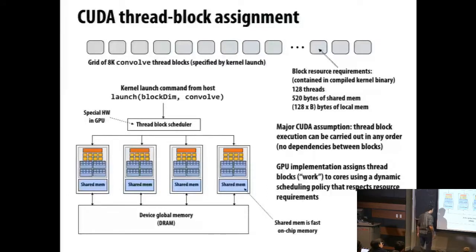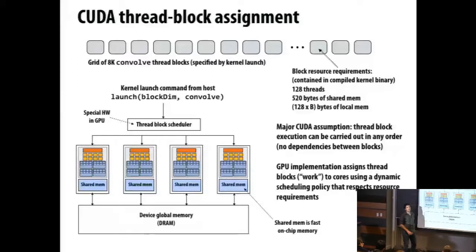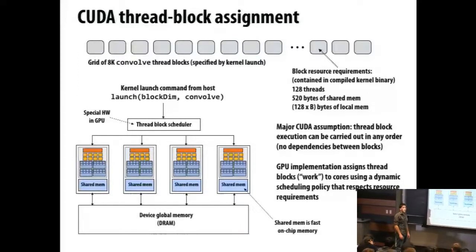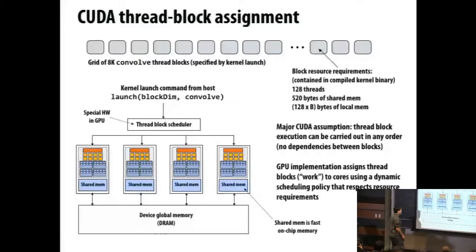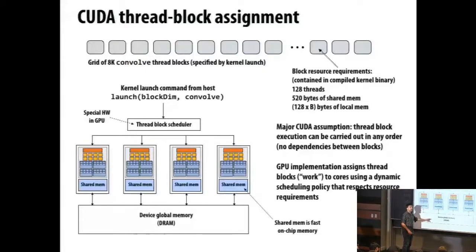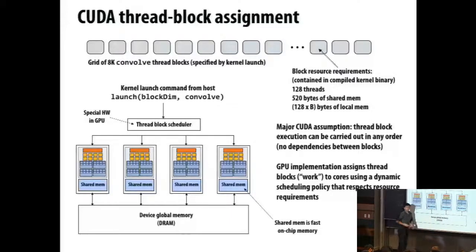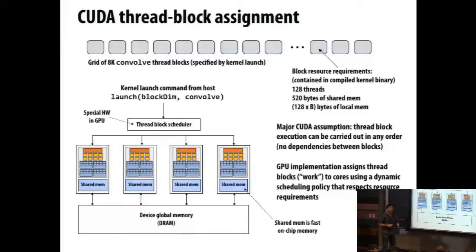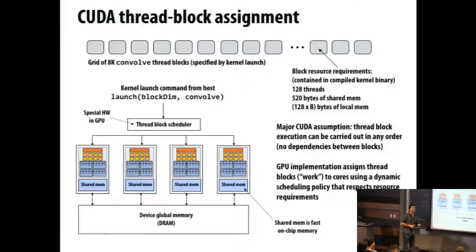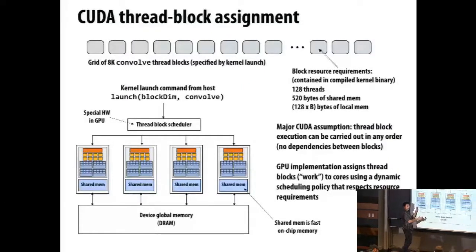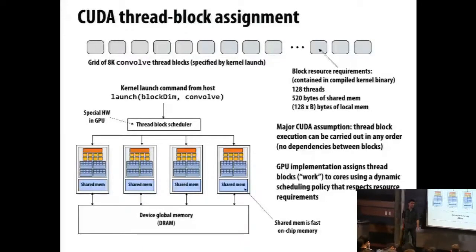There is certainly no implementation of any modern GPU scheduler that I'm aware of, or really too many CPU hardware schedulers that I'm aware of, that make any of those real-time guarantees. One thing that will certainly happen, and I'll get to this in a second, is we're not going to oversubscribe the chip. You should think about this as every one of these cores being a worker, and if it's doing something, I'm going to give it one job, and when it's done with that job, I'll give it another job. So you're not going to have a lot of interference between these things. To be real time, I would make my kernel small enough so I know every thread block got done in a short enough amount of time.